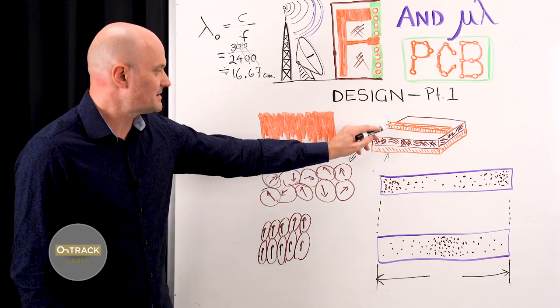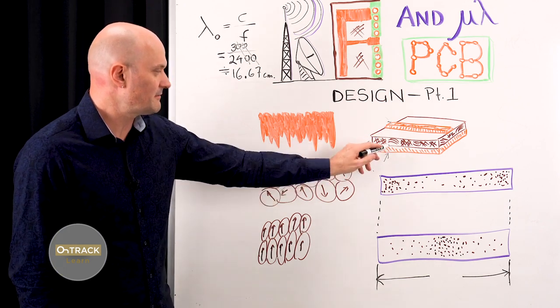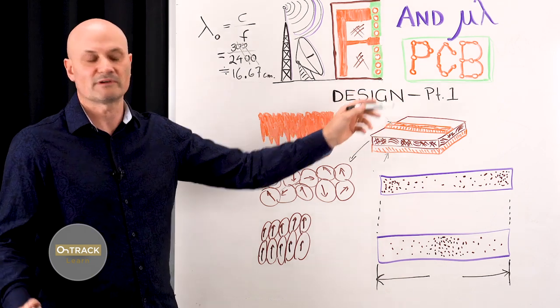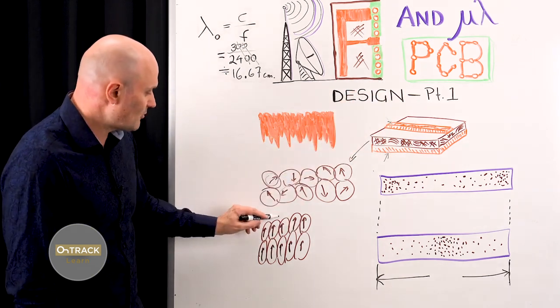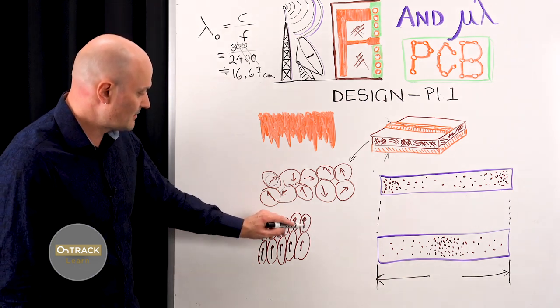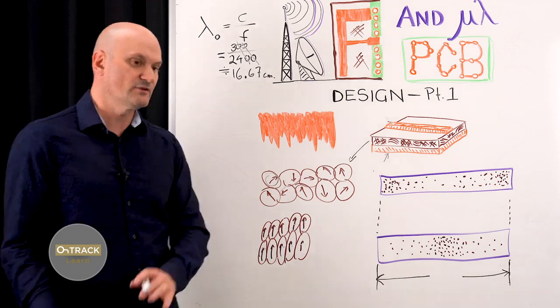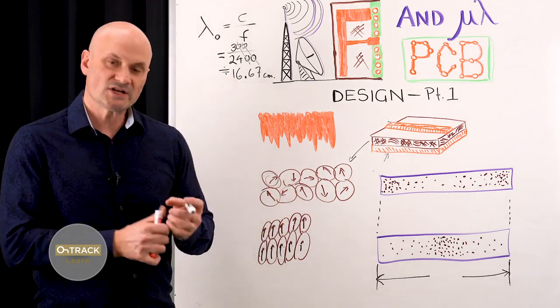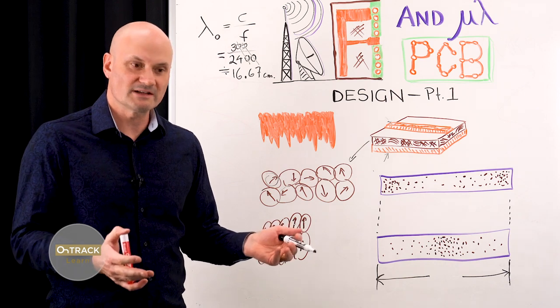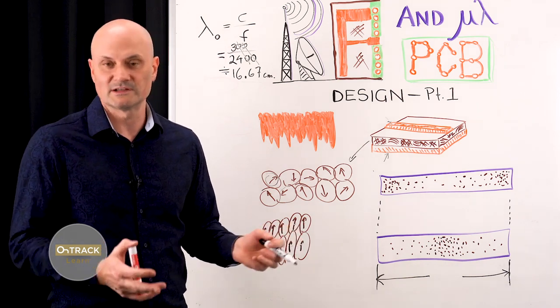And when you put a voltage between two conductors, so the trace and the reference plane is 0, and we have a pulse voltage on the trace, say 3.3 volts, where that voltage exists, we're forcing the molecules in the insulator to align their charge domains, because like charges repel and dissimilar charges attract.